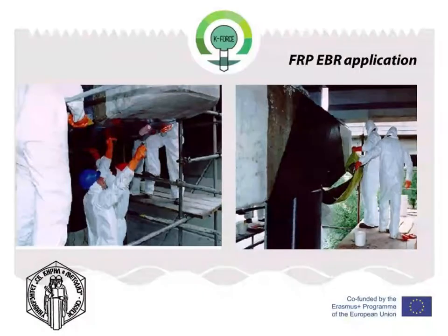The adhesive is applied to the FRP strip in a dome shape, having slightly more thickness along the center line of the plate. This reduces the risk of forming voids when the strip is applied. The strip is offered to the concrete surface, applying pressure by means of a rubber roller to ensure intimate contact with the concrete. The extra adhesive should be squeezed out along the sides. The final bond line should be of equal thickness along the strip.